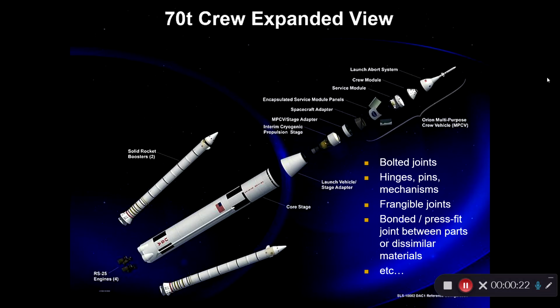We've talked about before the fact that a complicated structure such as NASA's Space Launch System is composed of lots of different parts, and a lot of the uncertainties in the model come in the joints between the parts. And so those are often some of the variables that are being updated, the stiffnesses in bolted joints. For example, in SLS, there are bolts between flange joints with bolts possibly between a lot of these different sections.